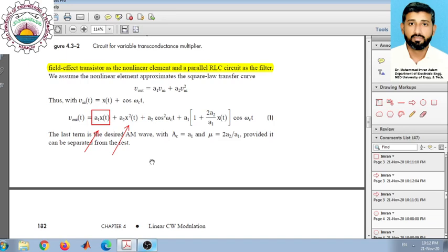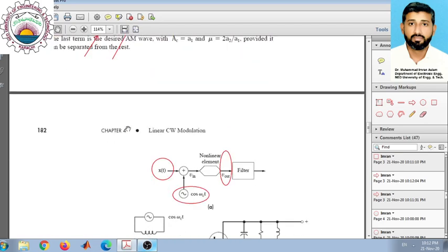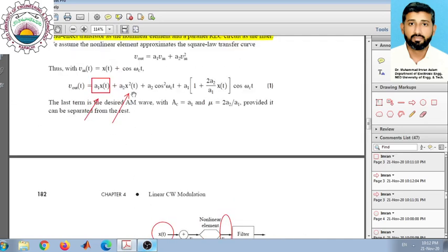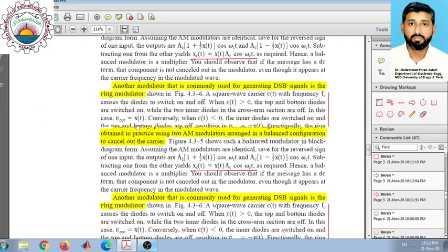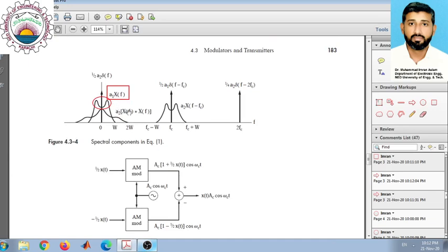We know the standard property of transforms, that if we transform from time domain to frequency domain, this x square t would become a convolution. So that means in frequency domain we are convolving this xf with the xf. So the second signal would be this convolution of xf with xf.